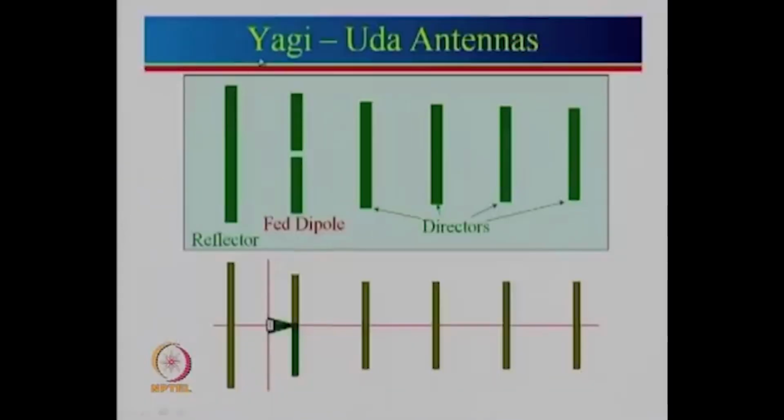What was popular was, instead of a normal dipole, they used a folded dipole. The advantage of a folded dipole is that the input impedance is increased by 4 times, and this was fed by the twin cable which had a characteristic impedance of roughly 300 ohm, which provided a good impedance matching.